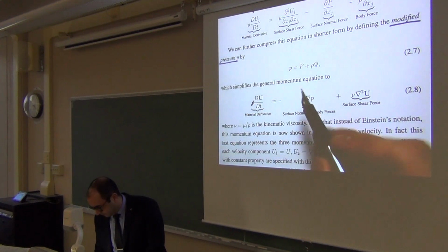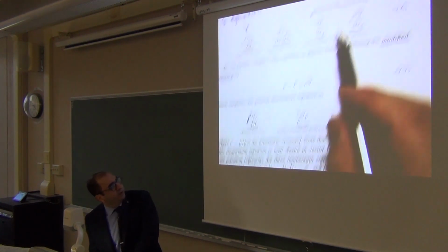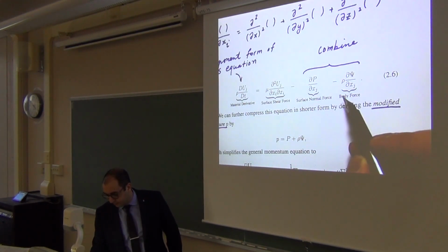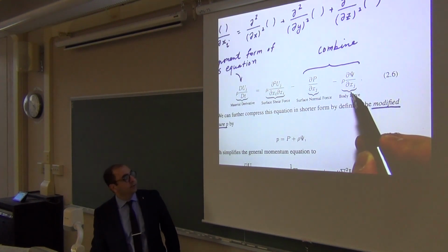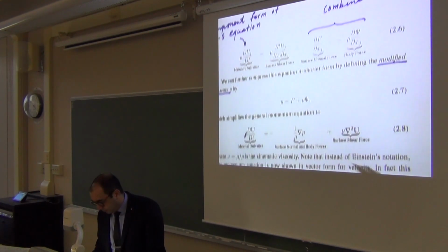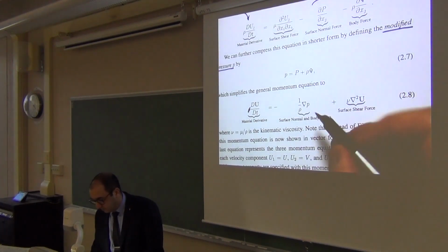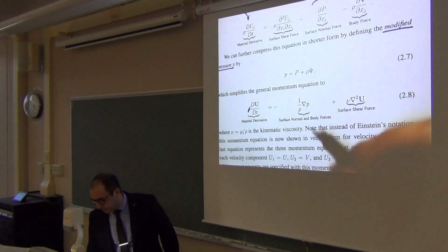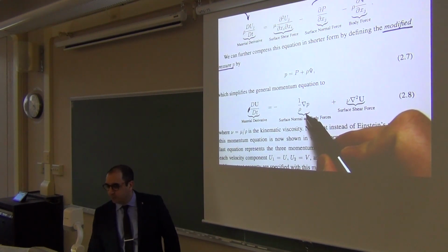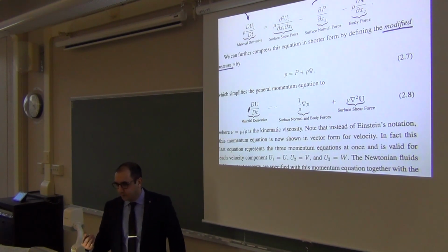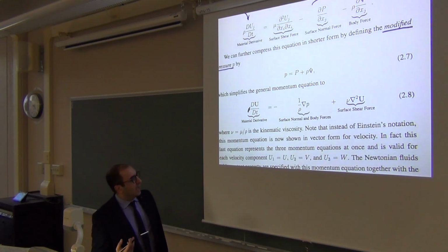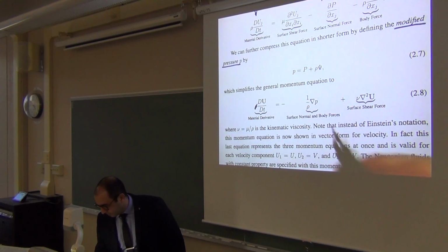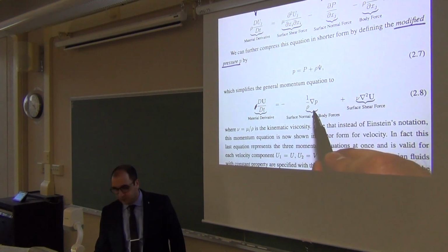Why? Because now I was taking the derivative with respect to one of the components, x, y, or z, and that applies to both of these terms, right? xj, xj. So it's really taking the same derivative of the combined pressure, modified pressure, right? So that combined derivative in 3 dimensions can be represented by nabla or gradient. Remember, we talked about that? So gradient, nabla, the operator means 3-dimensional differentiation. So I can show this whole operation here with the symbol nabla.